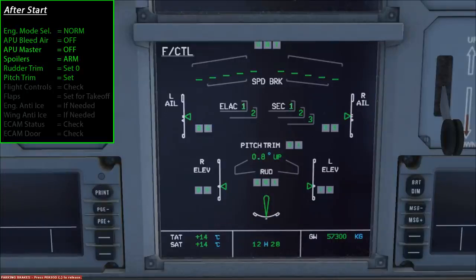check. Now, while you're sat in the cockpit, it's really difficult to look back at the wings to make sure that when you move the controller, the wings are actually doing the right thing. So pilots check their flight control responses through an electronic display like this. On this page, I'm going to move my joystick backwards and make sure that the flight controls do what's expected.